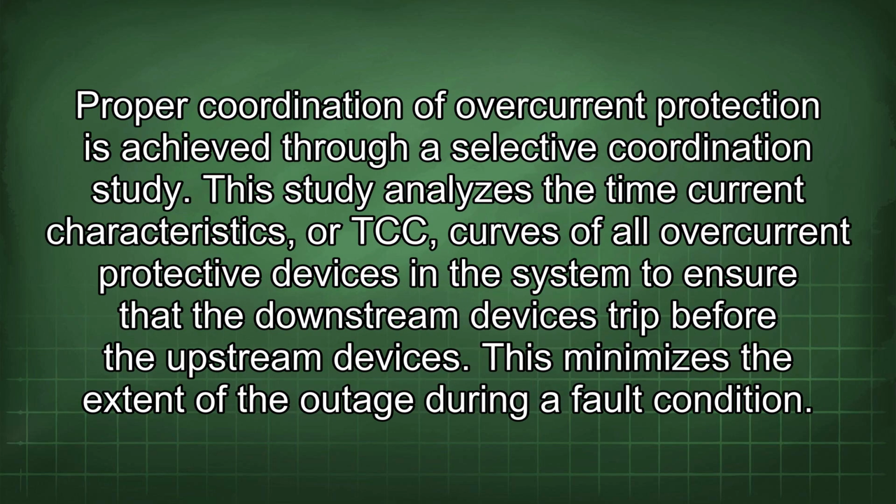Proper coordination of overcurrent protection is achieved through a selective coordination study. This study analyzes the time current characteristics, or TCC, curves of all overcurrent protective devices in the system to ensure that the downstream devices trip before the upstream devices. This minimizes the extent of the outage during a fault condition.